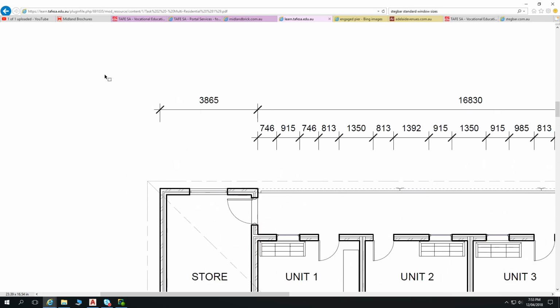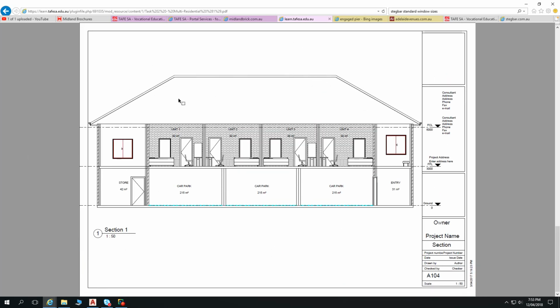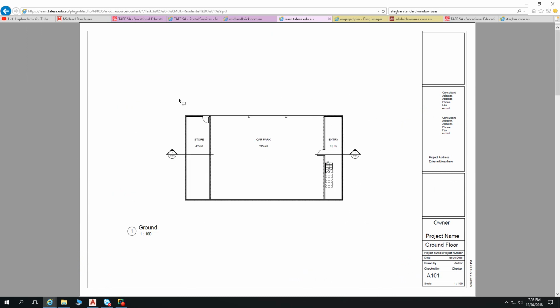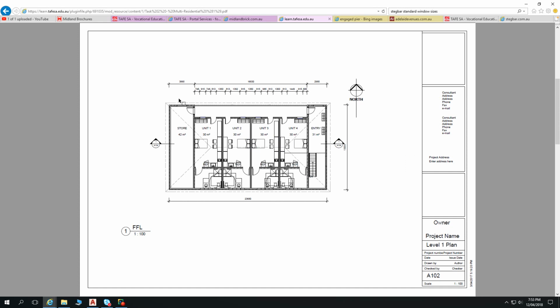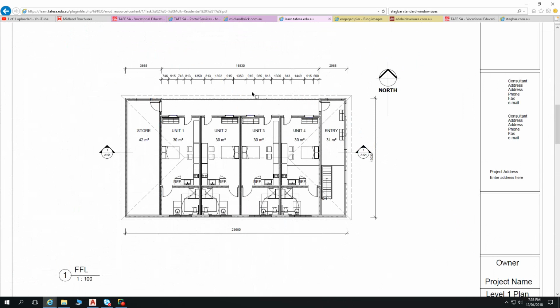What is it? 16.8 metres. That's certainly a very, very large span to achieve. So good luck doing it without columns. But for that car park there, we've got dimensions there. We've got 13.3 metres span back that way. You might not be able to achieve that with various different materials, and it might require introduction of other columns within that car parking space. It's probably good to mention that as a drawback with that particular system as well.